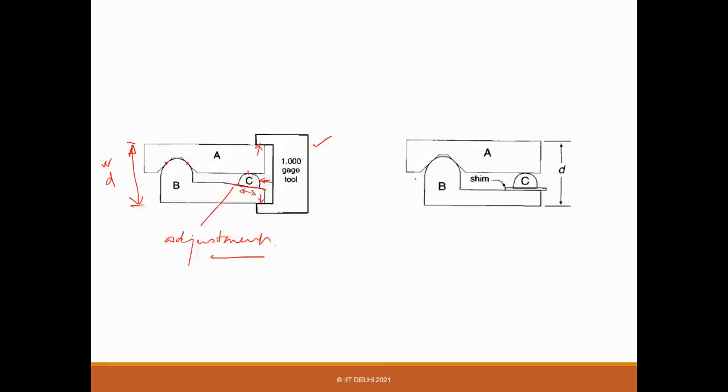The other way is, suppose you don't have a slope, and this is the thing you have in the other embodiment. Suppose you know how much is missing, right? If you know this inaccuracy, you just choose a shim of that dimension, right? So suppose it's 0.001. You take a shim of 0.001 and then assemble it. You will get it, right? So every time you do, you get the same thing.